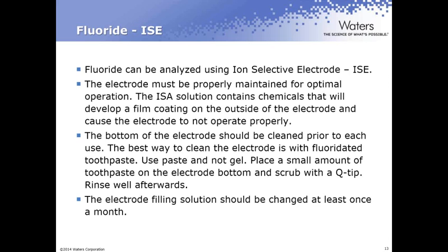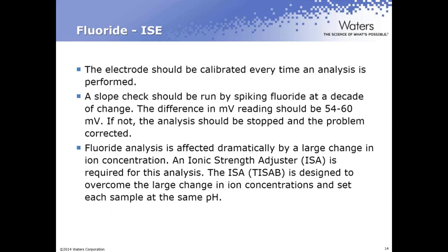It's also a good idea to change the filling solution on your electrode at least once a month, and more often if you run that electrode analysis more often than maybe once or twice a week.